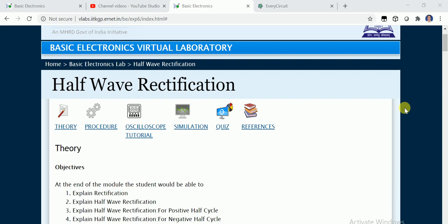In this laptop charger or mobile charger, the first thing we require is a transformer, because the voltage coming into your household is 220 volt, 50 hertz alternating current, but the requirement of the DC is 15 volt or 5 volt or 10 volt or 12 volt. So the first thing we require is a step down transformer to reduce the voltage.